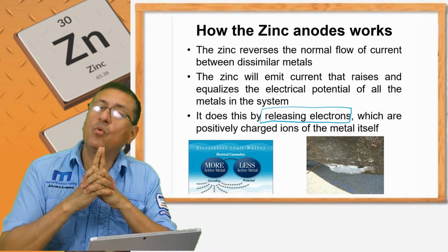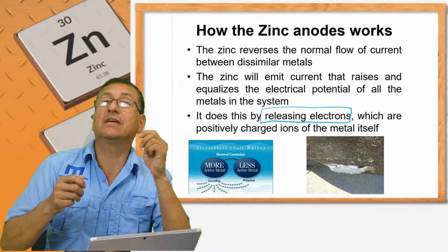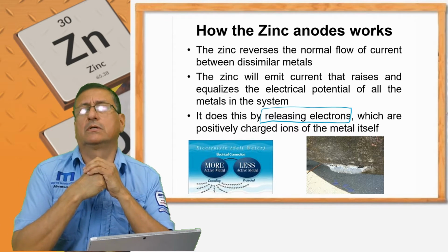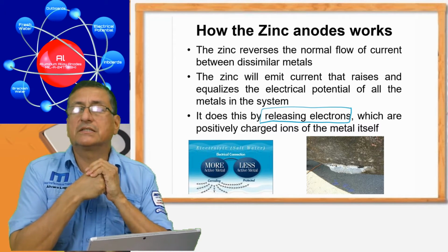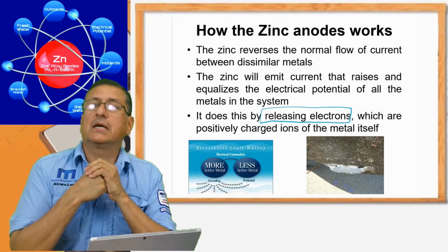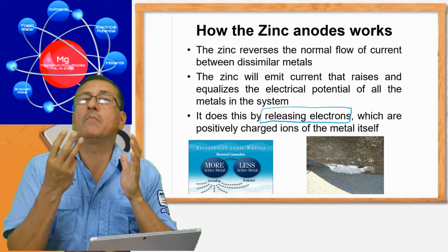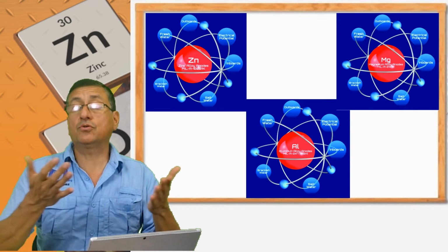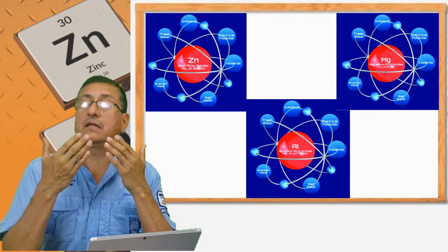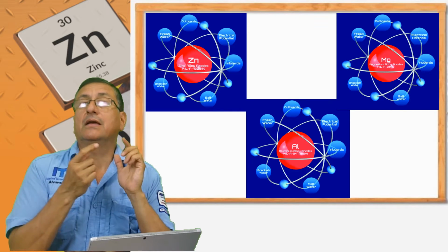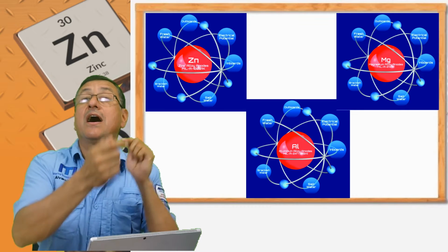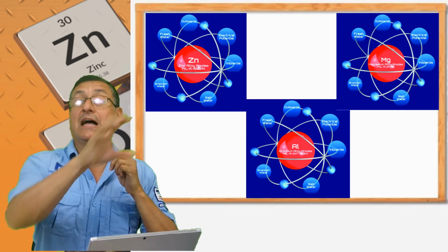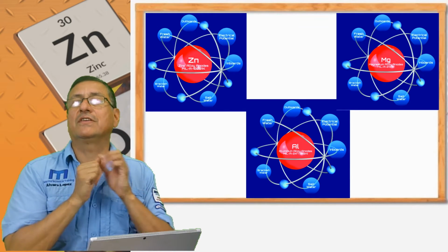And we are going to check which material, which alloy, creates higher potential difference. In general, we are going to use three types of sacrificial anodes: aluminum alloys, zinc alloys, and magnesium alloys. Those three alloys are used as sacrificial anodes. Depending on the water and the material of the hull, some sacrificial anodes create a higher differential potential. The higher differential potential is good because you accelerate the attraction of oxygen on the sacrificial anode and you protect the metal.